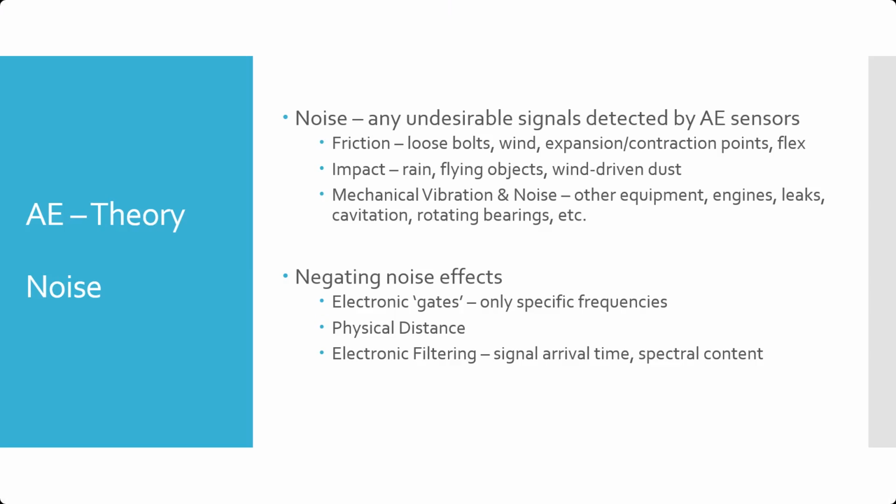There are things on some of our airplanes, right? An APU, a lot of APUs turn somewhere between 50 and 60,000 RPM. That's getting into the ultrasonic range. So just the spinning of the APU is fast enough to create ultrasonic sounds. Even your large engines are spinning at 10, sometimes 15,000 RPM. Right? If you have a turbocharger, some turbochargers can spin close to 100,000 RPM. Just to give you an idea, 60,000 RPM is 1,000 rotations per second. That gives you some idea of how fast these are turning. Hard to kind of wrap your head around it.